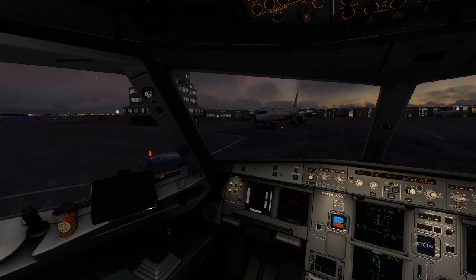We have the frequencies and we have noise abatement procedures as well. The direction in which aircraft take off and land is determined by the surface wind speed and direction and the potential runway system. The term runway in use shall indicate the runway that at a particular time is considered by ATC to be more suitable for use.